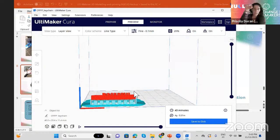The best way is to have it laying on the ground, as I could with this particular object, and then I would not need supports. But just to tell you that if you have an object which has bridges or angles, it is no problem. You can ask it to make supports.